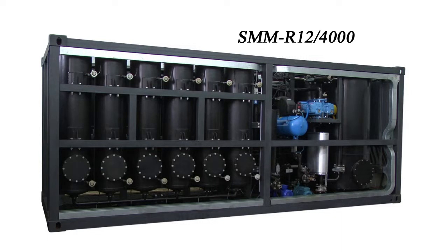After regeneration, the oil goes to a filter for final purification from solid impurities and filtration of oil. After sorbent saturation by the products of oil decomposition, the system switches to sorbent reactivation mode. The sorbent is reactivated by igniting it and creating a strong airflow over it. Heating causes the sorbent to ignite, which purifies sorbent pores.